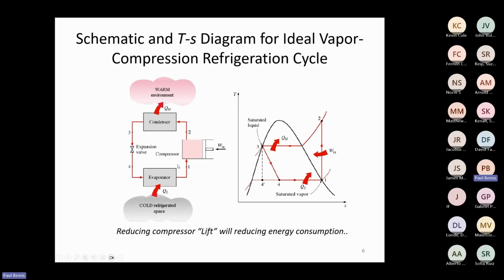If you look at it from a thermodynamics point of view, this is a temperature entropy chart. Many of you may remember this from thermodynamics if you remember that far back or have seen it. But this is the temperature entropy diagram. The most important is here 1 to 2. In my mind, work, shaft work. You see it on the left-hand side, work in. I'm compressing a medium gas to get it hot so I can dump it to the atmosphere. So the temperature here, T2, it's got to be high enough so that I can dump. So if the outdoor air temperature is 110 degrees, I've got to lift, they call it lift, and the lift comes from this pressure right here.